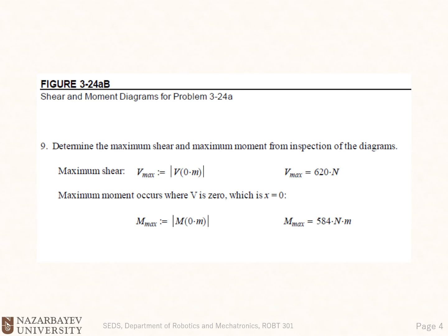And at that cross section, for sure, we will have the maximum stress. When we have the maximum stress, at that point we will have the lowest safety factor, and the safety factor should always be more than 1. So this is the main reason we do the beam analysis, and we are basically concerned with the cross section with the maximum shear and, specifically, moment.